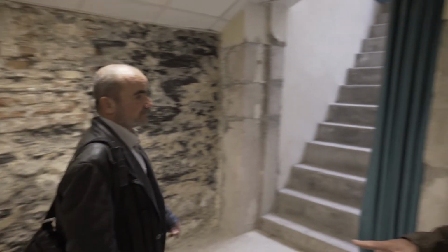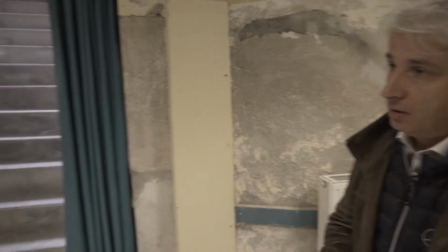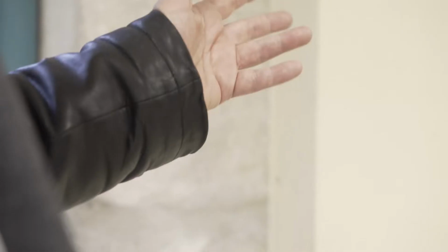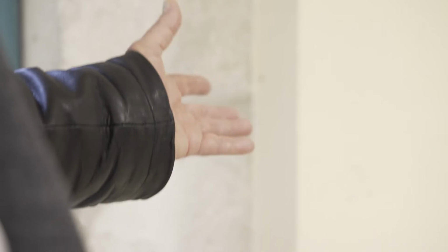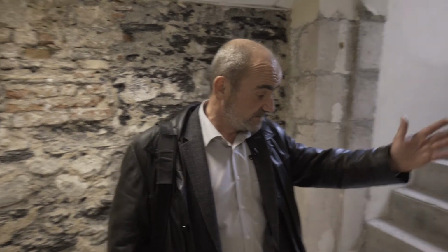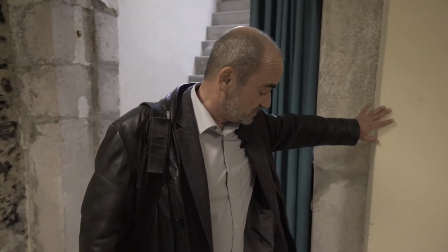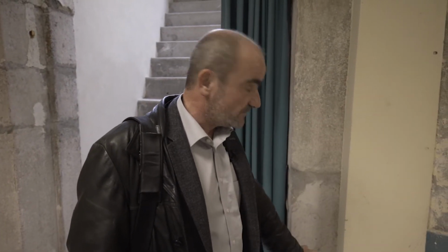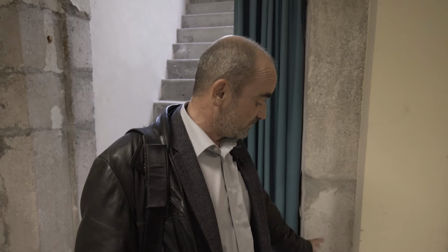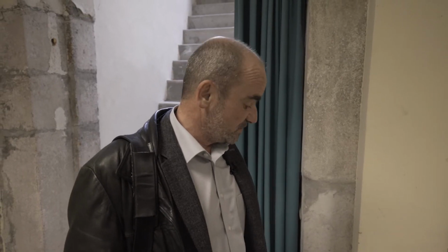We are currently in the basement of the building, in a room that we want to renovate as a music practice room. Right. This is very interesting, because it could be an opportunity to combine this renovation with protection against radon rising from the ground. It will be important to ensure the best possible airtightness of the lower floor. For example, on this existing technical shaft, it will be wise to dismantle it in order to carry out sealing work at the level of the service connections.